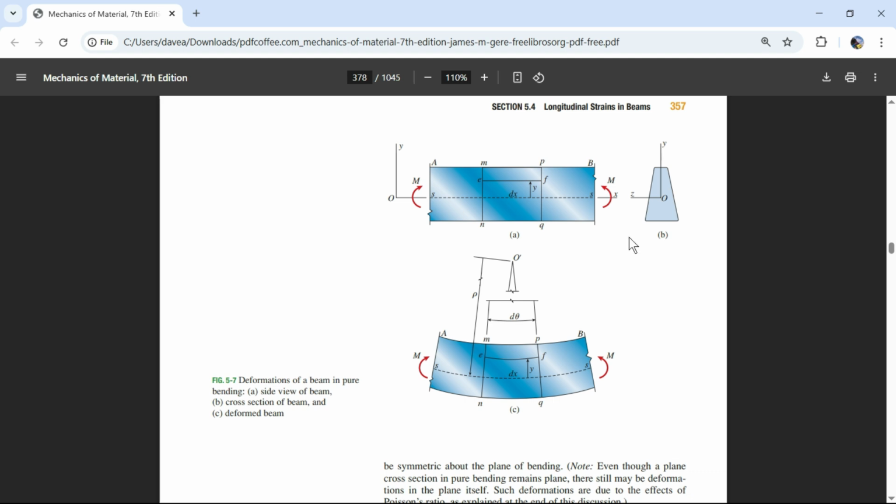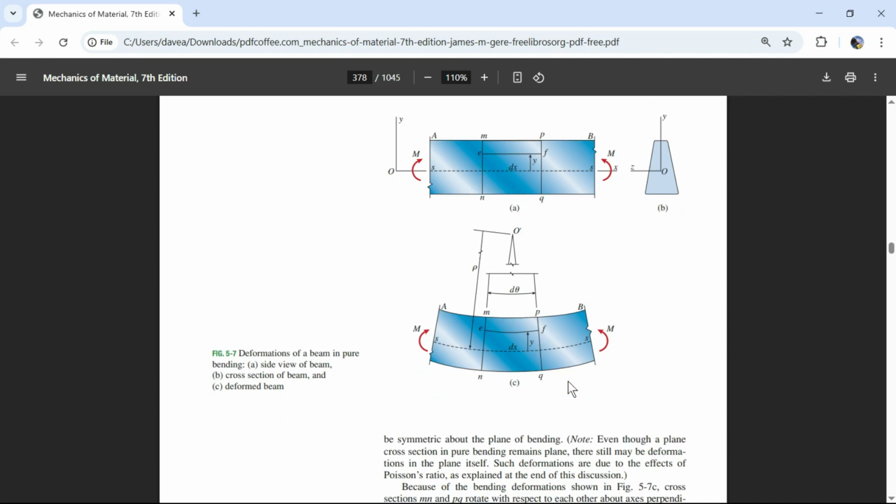All right, so we're back, and I'm glad I took a little break because this part isn't so intuitive to me. But if we have a constant moment, and you can do this with a flexible ruler, twist the ends with your fingers, and then all throughout that ruler you're going to have that constant torque due to the moment that you're applying at the ends.